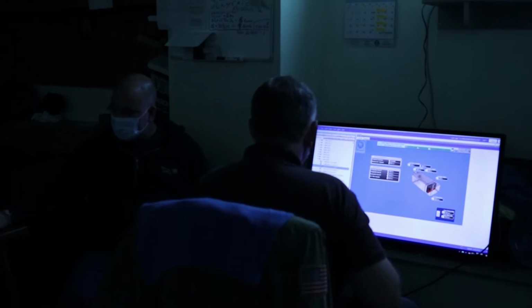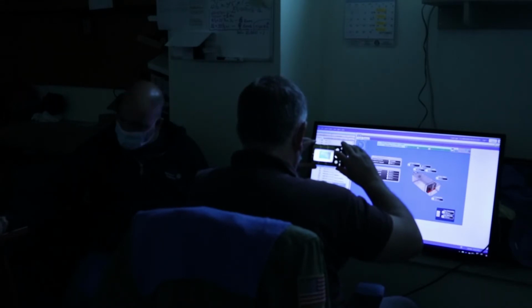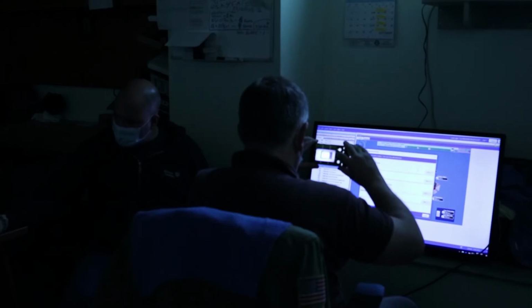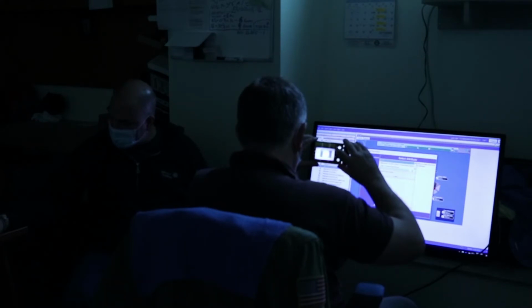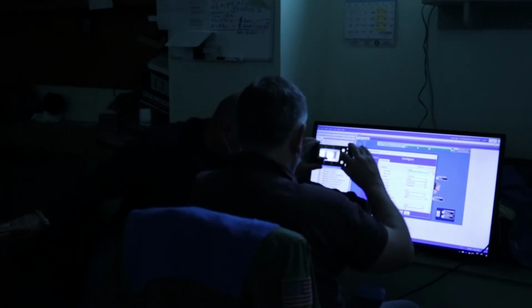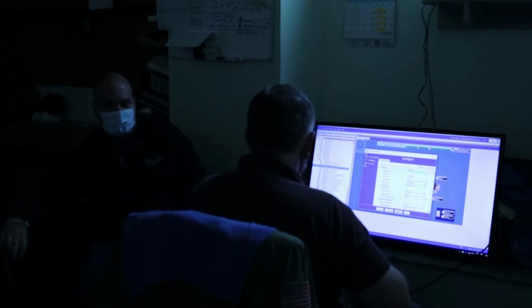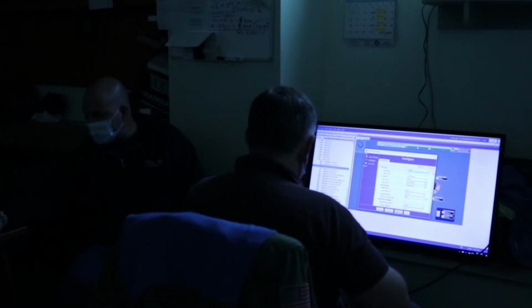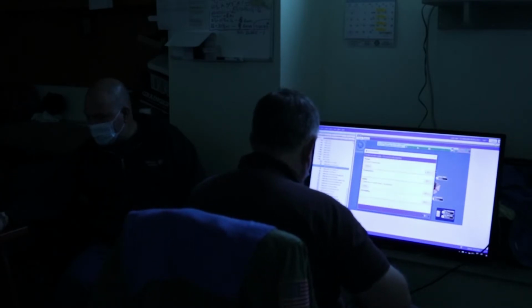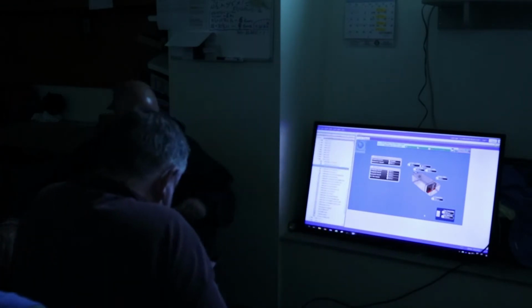Once I'm there, I highlight it, right click on it, and go to show extensions, and there's the trend. So I click on new. If you want to name the trend, you can change it up here. Then I go to next, and here's where I put my information: the amount of time that I want to do it for, and whether I want to keep the data longer than 24 hours, which is the repository. So I enable or disable the repository. Sound good? Yes, absolutely. Can you delete this trend? Absolutely. It's every half hour, it's not a bad thing.